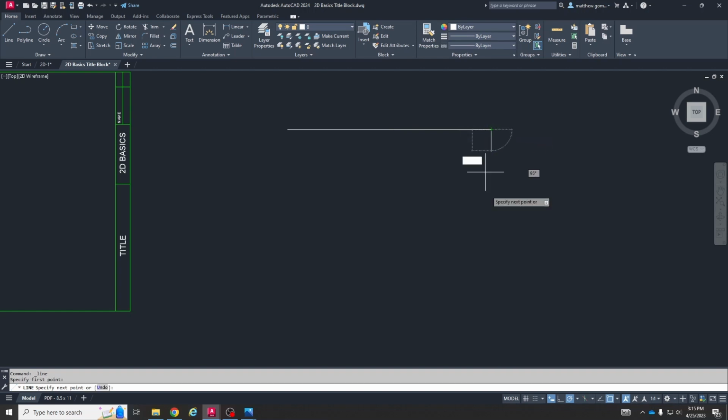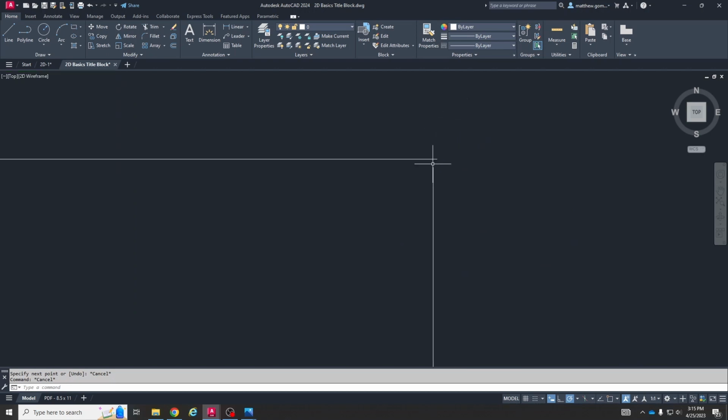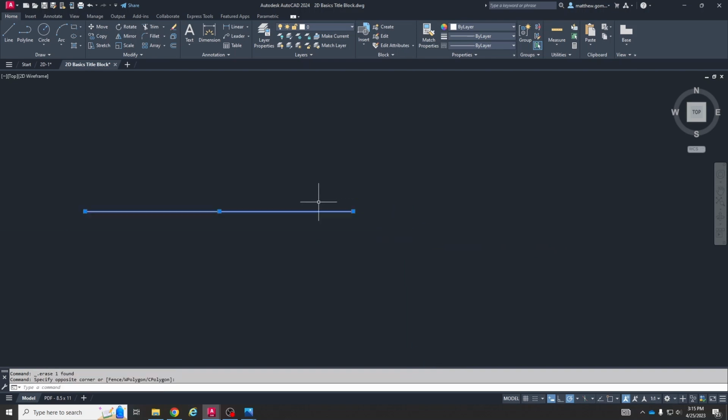make sure we have on, because it allows you to just draw lines connecting to others. If you don't have that on, you can draw one line perfectly fine, however long you want it. But then when you try and connect another line to that, there's nowhere to snap onto. So you can get it pretty close, you click, and then you're like, oh, that looks pretty good. And then as you zoom in to further inspect it, you realize there's a gap, or sometimes they'll overlap or something like that. So we want to have object snap on.